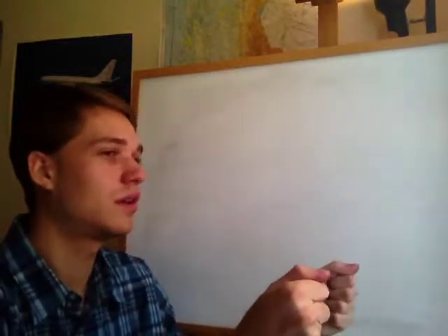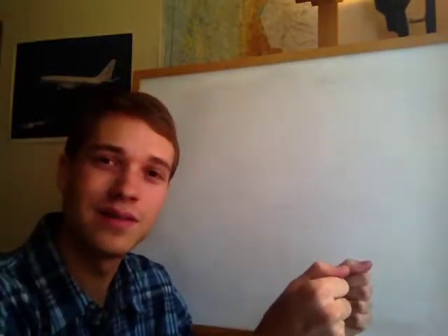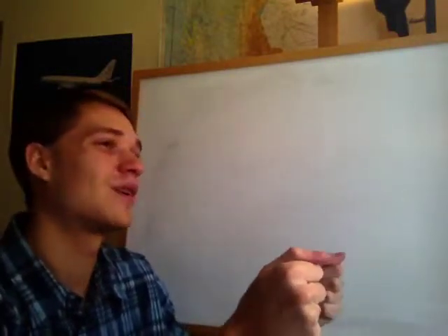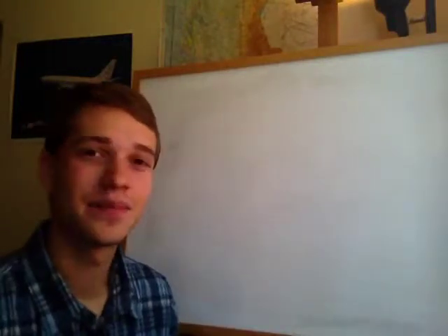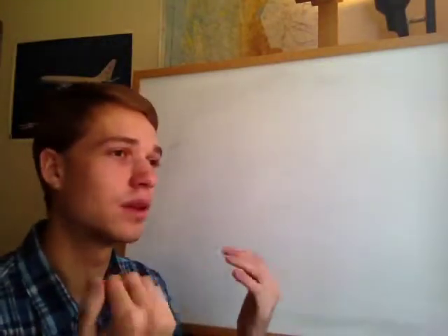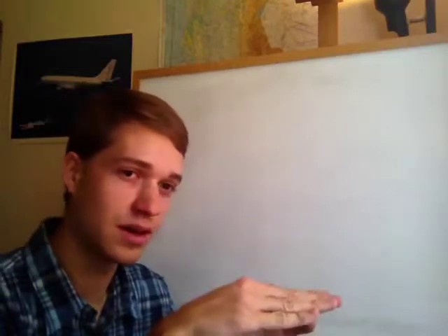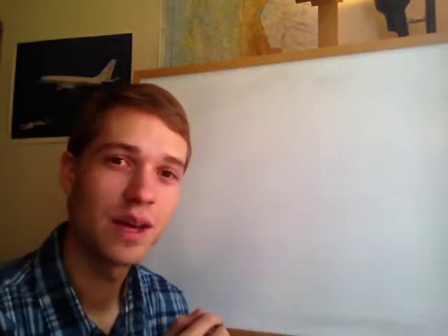You're having to hold pressure against the controls, and you've got a 3-hour flight in front of you, and you don't want to have to hold pressure on the controls for that whole time. The reason you're holding pressure is that your airplane is going faster. You're producing more lift on the wings, so you have to lower the angle of attack so that you don't climb. So what do you do? That's what we have trim for.